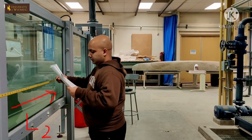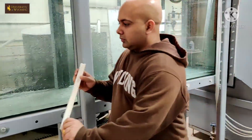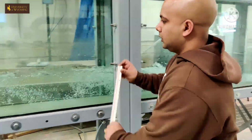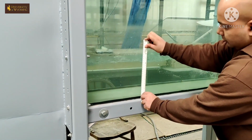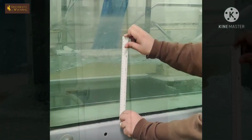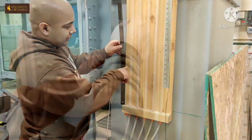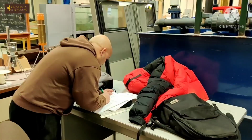After the hydraulic jump is stable, we'll take the measurements of L1, L2, LSJ and Y0, Y1, Y2, Y3 using rulers and tapes. In the end, we'll note the values in our observation table.